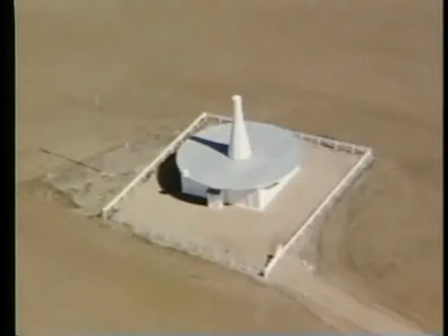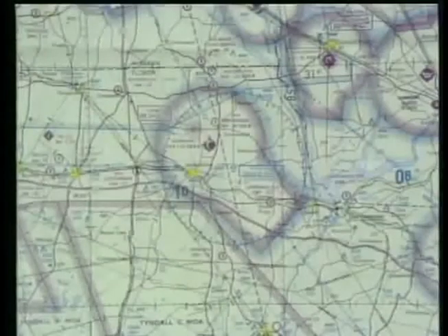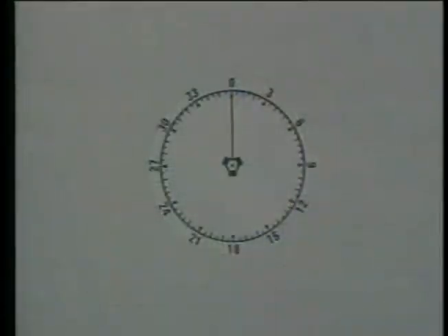A VOR station continuously sends out signals that are received by a radio in your airplane. The station is shown on an aeronautical chart by a compass rose surrounding its location. The compass rose is a graphic depiction of the signals transmitted from the VOR. These signals, called radials, extend out from the station and are numbered clockwise from magnetic north. Although the number of radials is infinite, only 360 are used.